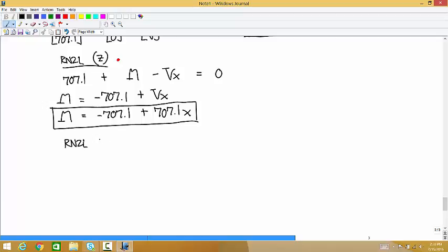And then the moment equation about the x-axis, we just have the negative 5,000 and the fancy T. So we get the same thing we did before, that the internal torque is equal to positive 5,000 Newton meters.